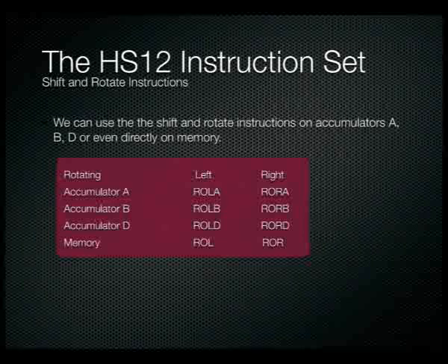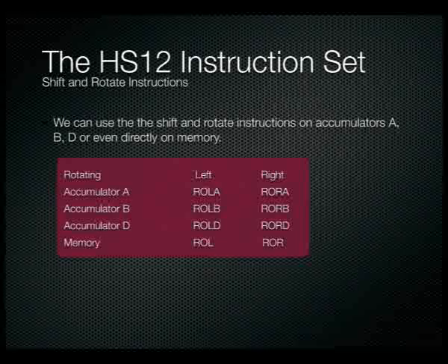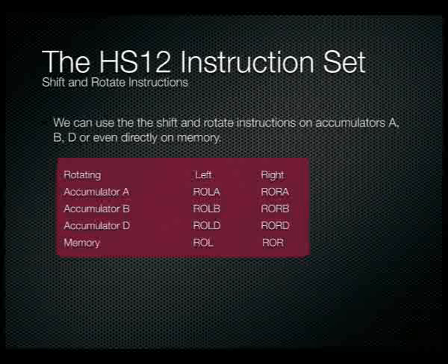So in situations where you want to shift the value through the condition code register, but you want it to be back to its original value after 9 shifts, then you might want to use a rotate. Rotate will effectively rotate your register through the condition code register and back into itself. So effectively you've got a 9-bit rotating register. The LSB slips off the end, goes through the condition code register and back onto the register, after 9 rotates left or right.